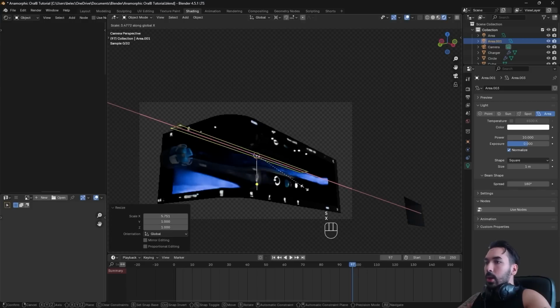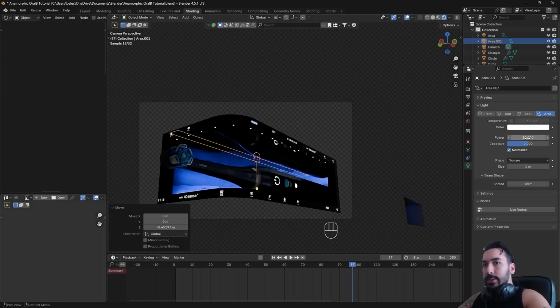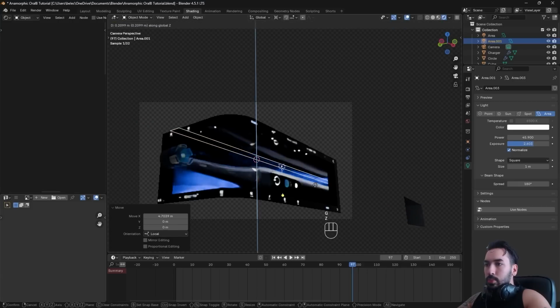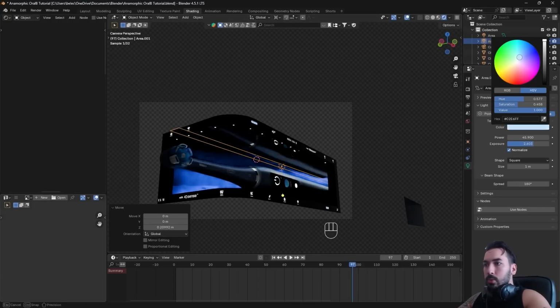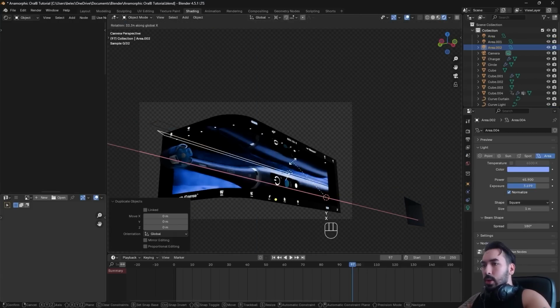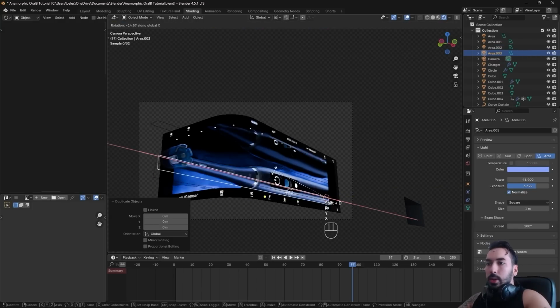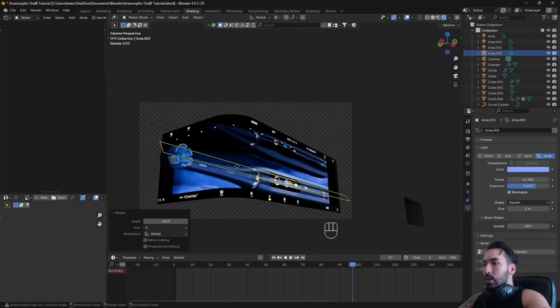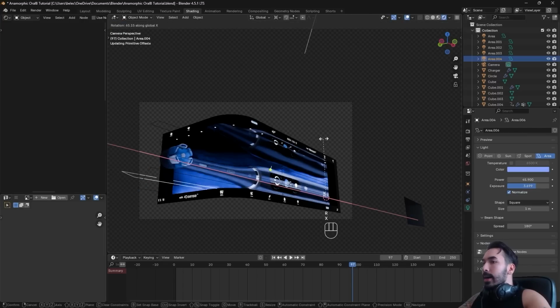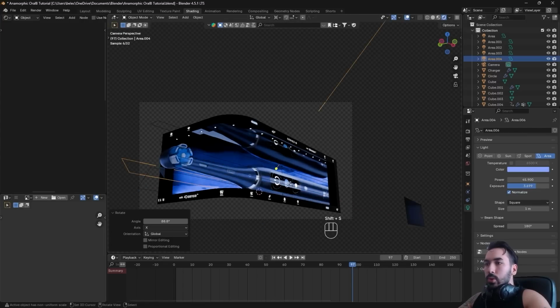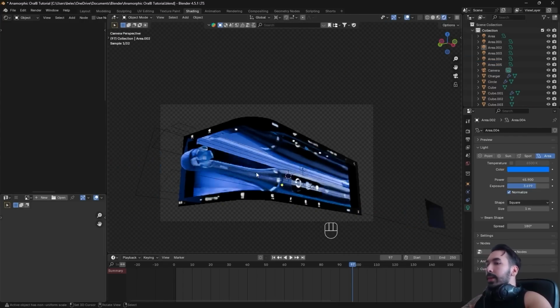So I'm going to place one long area light above the toothbrush like this. That's going to light up the side of this toothbrush, and of course we're going to make that a little bit blue. And then I'm going to duplicate it a couple of times because I want to have a few more of these reflections. I want another one over here. I want another one in the front like this. So now I got 3 bars of reflection. And then we're also going to do another one behind the toothbrush, so that's going to light up the edges of the toothbrush.